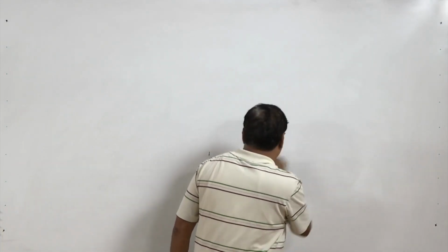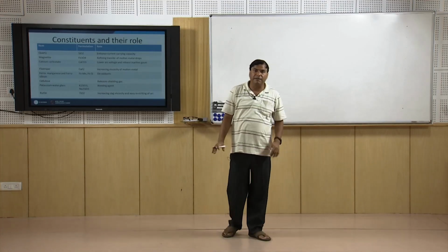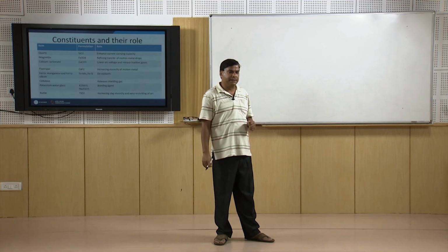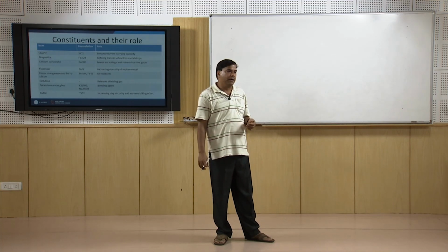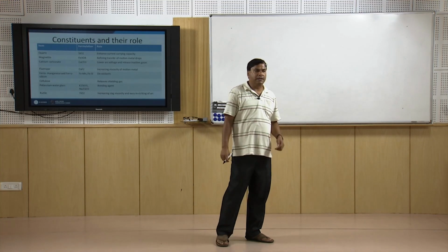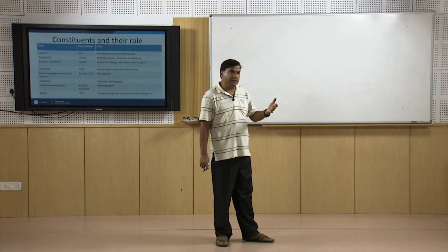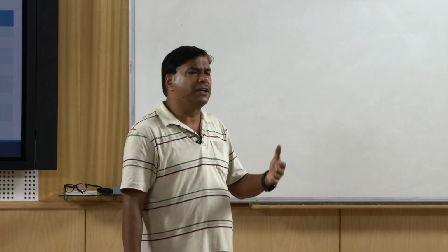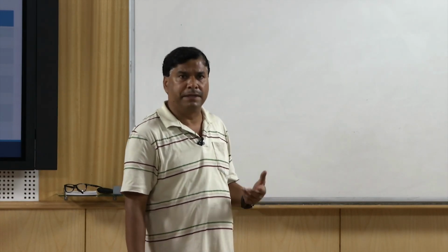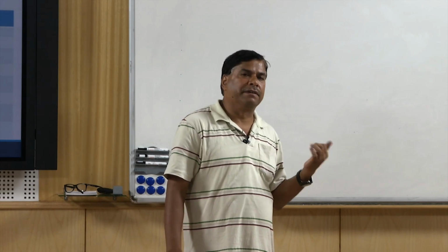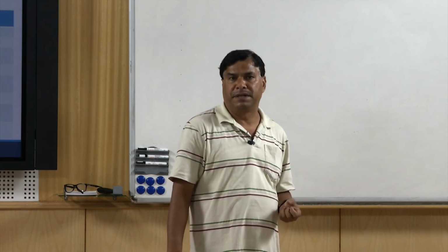So, now here I will conclude this presentation. In this presentation I have talked about the fundamental aspects related to arc welding, and three fundamental aspects I have talked about: the factors governing the melting rate and the effect of the polarity, and we have seen how the welding parameters affect the weld characteristics. Certainly the change in the amount of heat being generated will affect the solidification time and cooling rate experienced by the weld metal and heat affected zone, and these changes will in turn affect the structure and the mechanical properties of the weld joint.